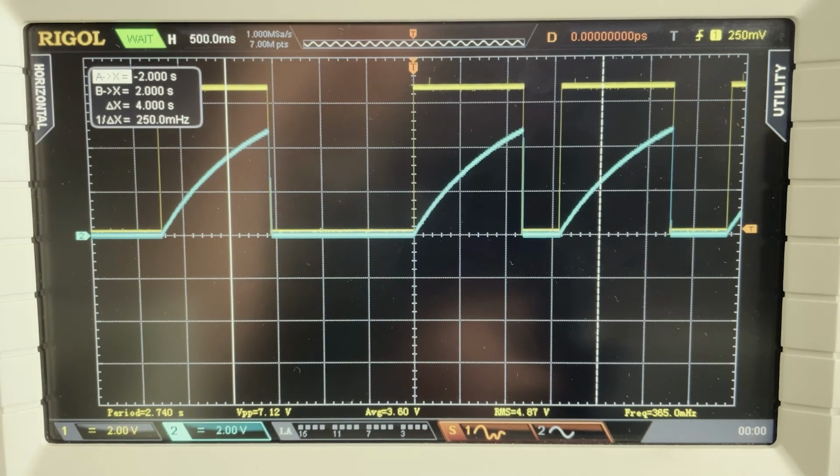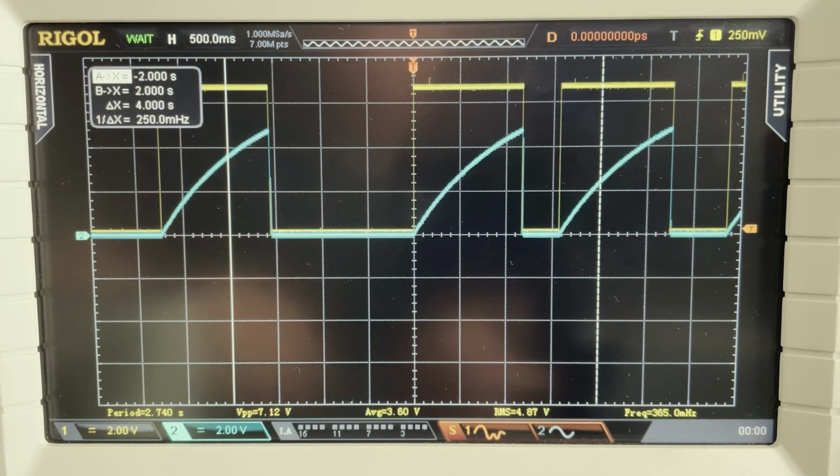That's all we have. It's something where you push the button, you get an output for a set amount of time, and if you want a longer time, you increase the resistance or the capacitance of your circuit, and you can make it so it lasts, honestly, as long as you reasonably want. There are limitations. You don't really want to get a resistor below like 1K, and if you get anything up in the mega ohms, you're going to start having problems. And kind of the same thing on the capacitance side, but it's generally pretty dang flexible. So that is what the monostable configuration looks like in its output in real life.